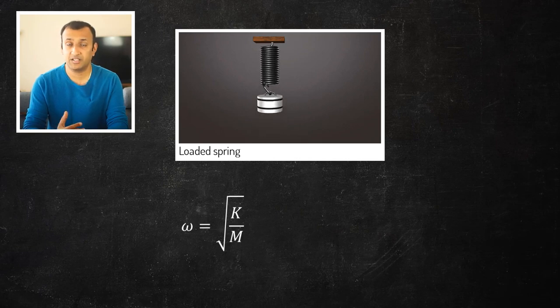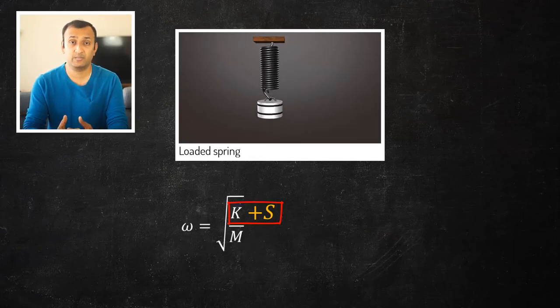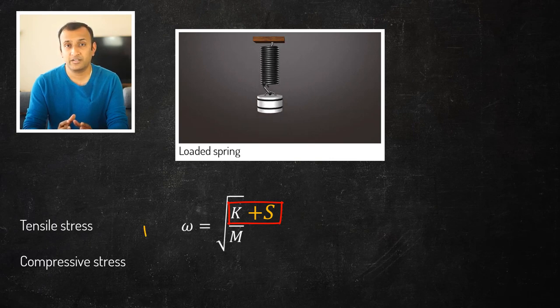When a structure is in a stress state, its stiffness changes due to stress stiffening. Therefore, the presence of stress in a structure can alter its vibrational characteristics. Typically, the tensile stresses increase the structure's frequency and the compressive stresses decrease its frequencies.